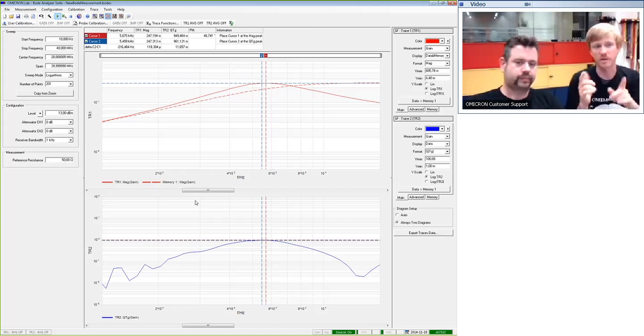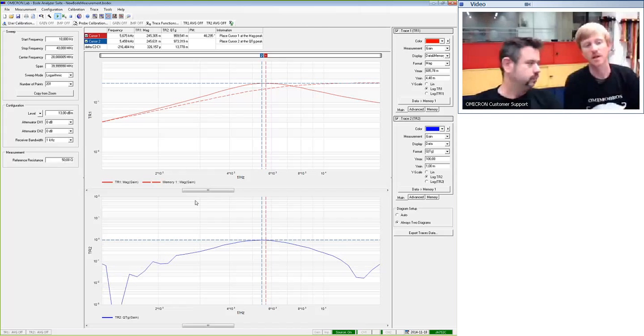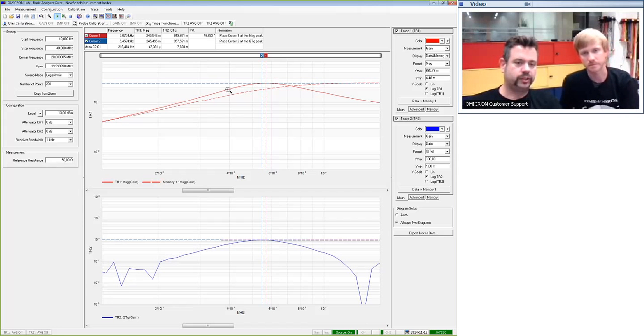And since we do not have that many frequency points in the curve, the cursor will probably jump a little bit more to the left, or if there is noise on it, a little bit more to the right, and this will already falsify our measurements. And therefore, we do a kind of optical thing. But as standard, you just go close to the curve, you say cursor 1, and you say jump to maximum.